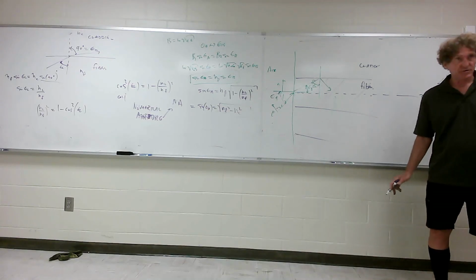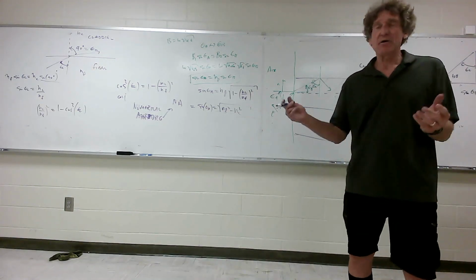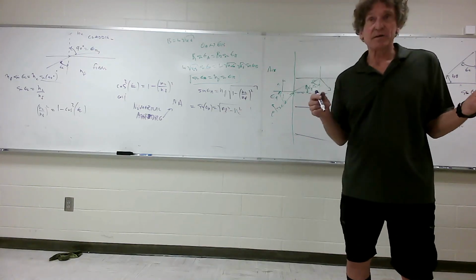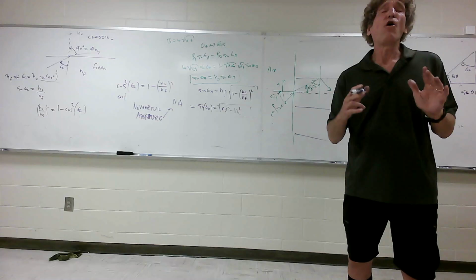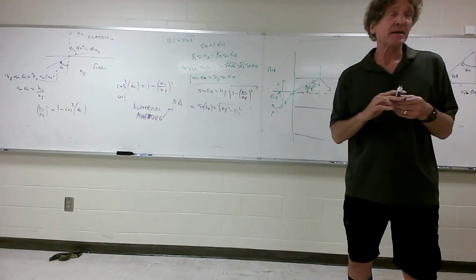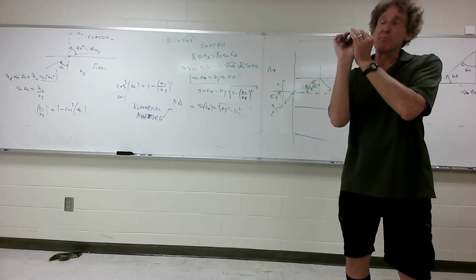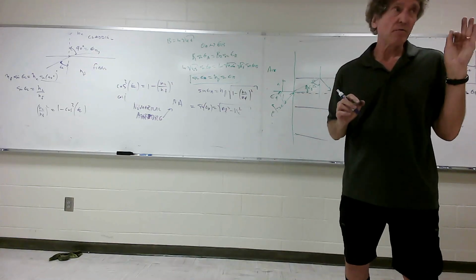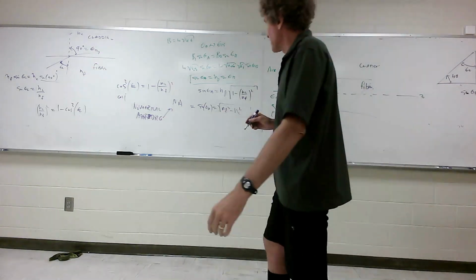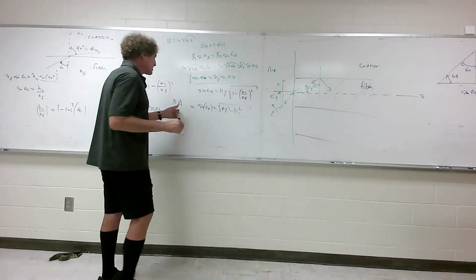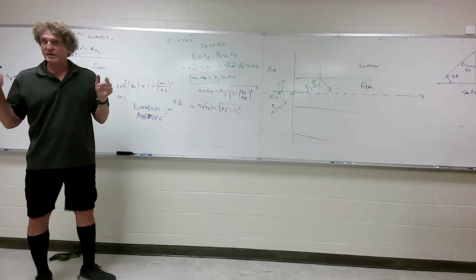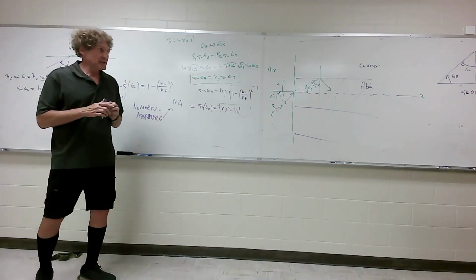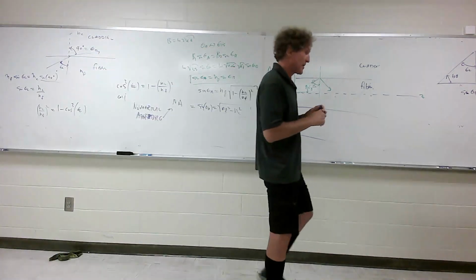Here's why numerical aperture is so important. Like n0 that he has there is the index of refraction of the media it's coming from outside the fiber. Guaranteed, it's almost always air. There may be exceptions when you have some sort of a plastic fitting or something keeping the spacing, but almost always it's air. It doesn't have to be, but almost always. That's as far as that. The numerical aperture is a measure of the, quote, goodness, how well it performs. The bigger it is, it means the less alignment you need with the fiber.